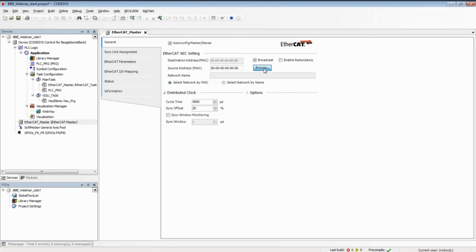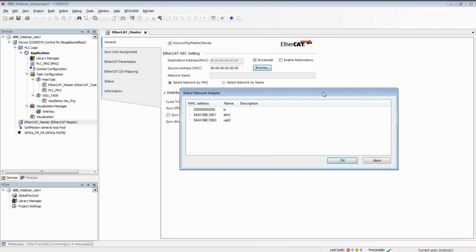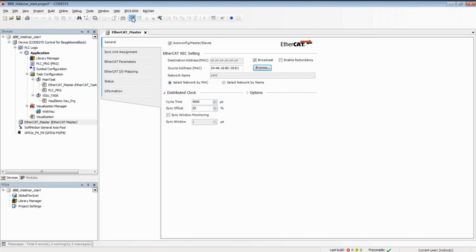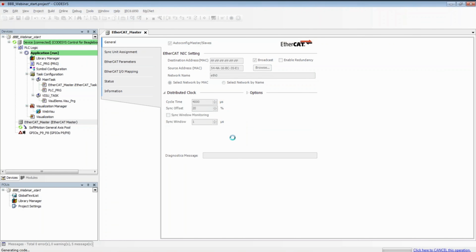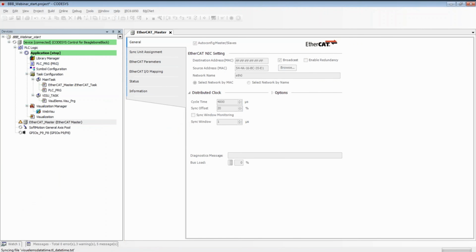Therefore, double click on that, browse the available ports, and see that there's one Ethernet port available here, the other one is an I/O and a USB port, so check the Ethernet port, and then I can download the EtherCAT stack. So my configuration has changed, therefore there has to be a new compile and download of the application, which is now a little bit longer, as the EtherCAT stack being prepared as a CODESYS library is now implicitly called and executed and downloaded to the device.